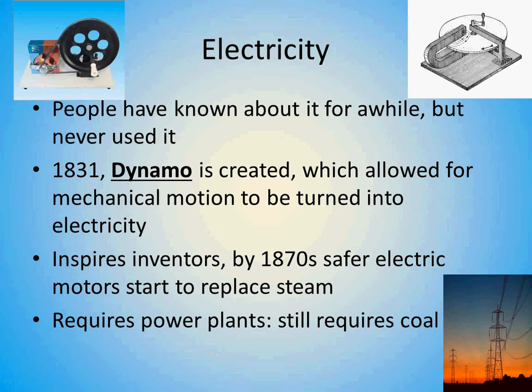During the early industrial age, though, around 1831, a dynamo was created. A dynamo takes mechanical energy. This is a hand crank version, but of course you can hook that to a water wheel. You can hook that to a steam power generator or whatever. You get something that can spin this wheel, and then this wheel through this belt will spin this over here. Now you've probably seen this N and this S. This is magnets. This is moving copper wire, but basically you just move copper wire and magnets. You could spin the magnet surrounded by copper wire, whatever, and you have an alternating electrical field.